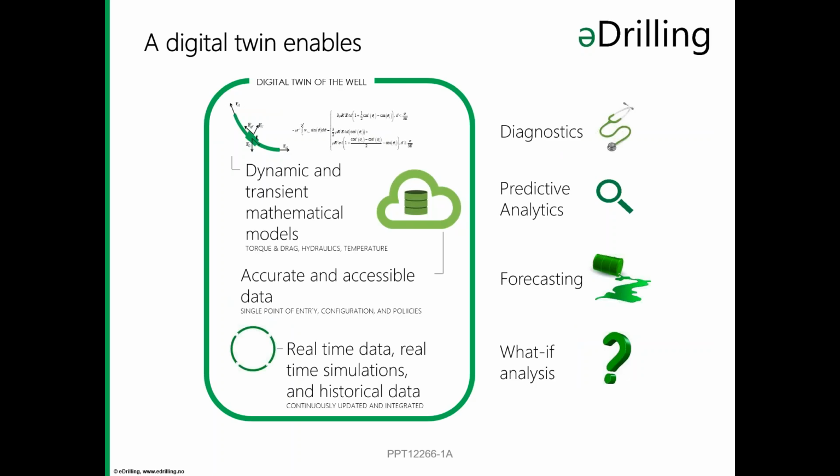So you now understand what the digital twin is, but having it actually enables additional features to help optimize drilling operations, such as diagnostics, where we do a lot of trend analysis on real-time measured data. We then compare it to our modeled data to give diagnostics and alarms to the end users. We also do predictive analytics, which are basically simulations ahead of time to look at how the well will develop. For example, we can do predictive analytics on cuttings development.